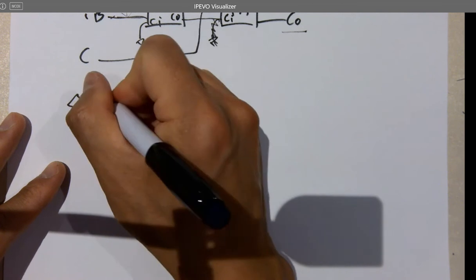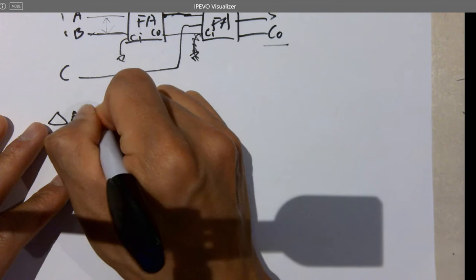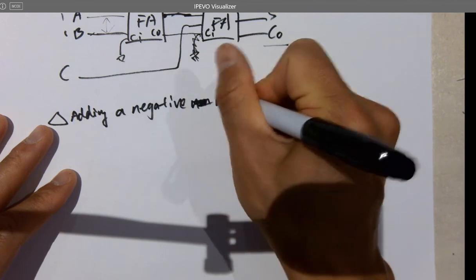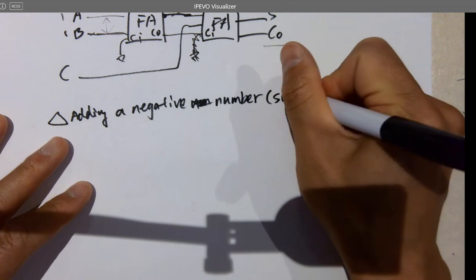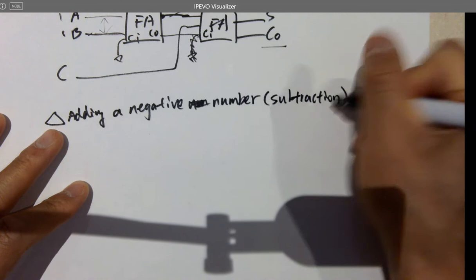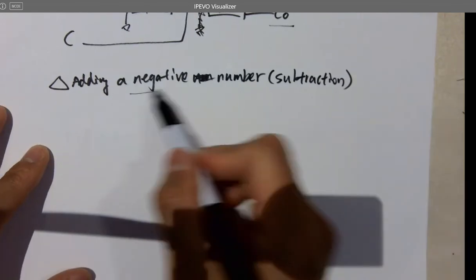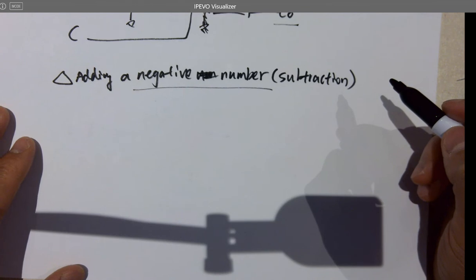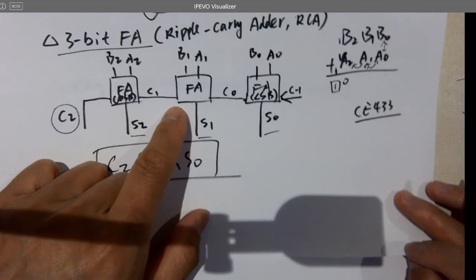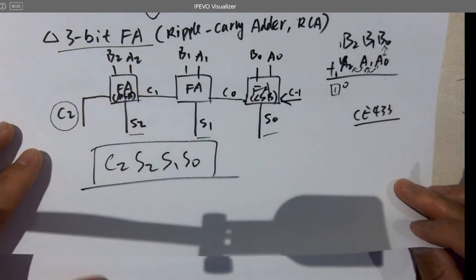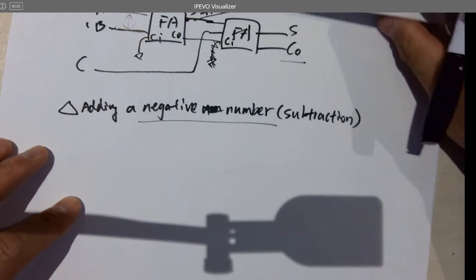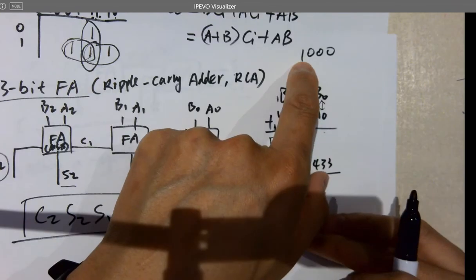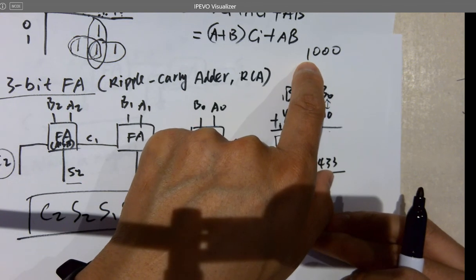Subtractor. When you are doing a subtraction, it's actually adding a negative number. Whenever you get a negative number involved, you want to use 2's complement. But the adder doesn't know it. We have to tell the adder what to do. The adder is able to add binary numbers and just do the operation. A negative number is still a binary number. You don't have to do some special things for the MSB here, right? I know it's a sign, but it's also a negative number.